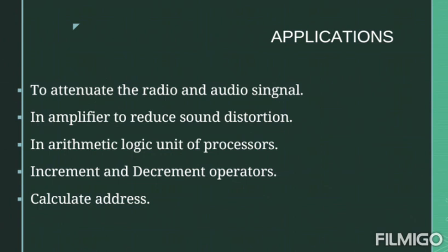So therefore, from the above half subtractor theory, at last we can conclude that by using this circuit we can subtract one binary bit from another to provide the outputs difference and borrow. Similarly, we can design the half subtractor using NAND gate circuits as well as NOR gates.